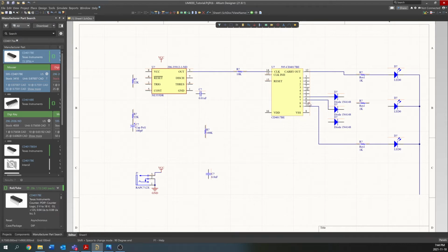You don't have to do this right angle way of drawing out the schematics. I believe Shift+Spacebar gives you different trace options, and the same command is true in the PCB editor as well. You can do right angle traces or however you want. I think there's a circular option as well. So I'll go for that. We'll put those together. You also see that as we're editing here, some of these designators get covered up, and you can always move these around after the fact.